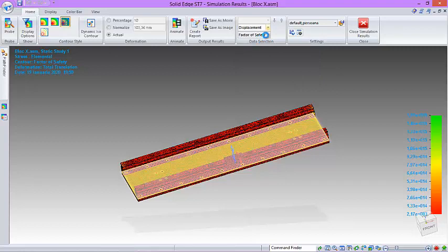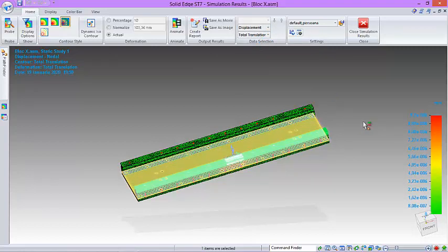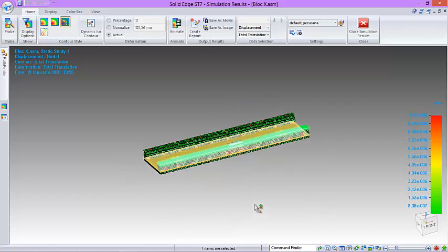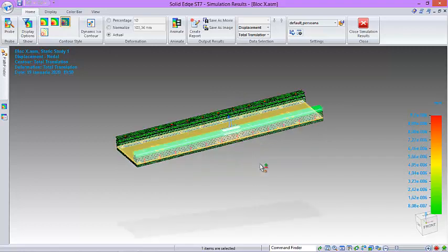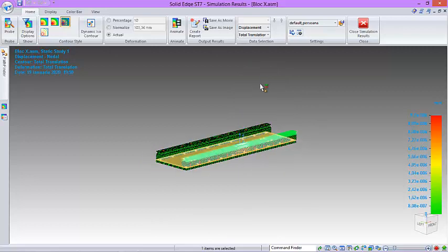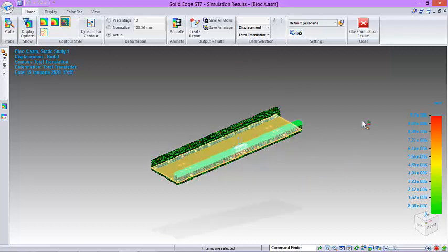And again, we're looking at a total displacement of 1 millionth, so it's e to the power of -6. So it's safe to say that this assembly is going to take the 35,000 newtons per cage, and we're going to estimate that it's going to take the 140,000 in total, and the best direction of that force to be applied would be on the Z direction of the vertical block when it's moving sideways. So it passes this test.